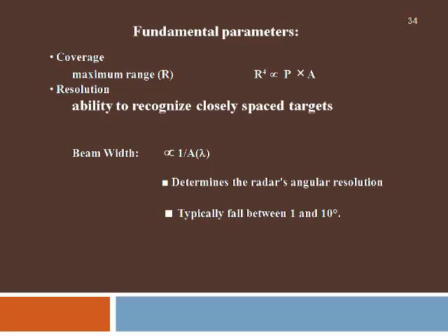Thereby, even with low power density of the echo signal, we will be able to give a good amount of input signal to the receiver by the high effective area of the antenna. Hence, parabolic antennas are good candidates because they have a very high effective area compared to the physical area.